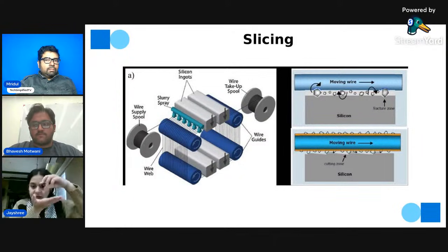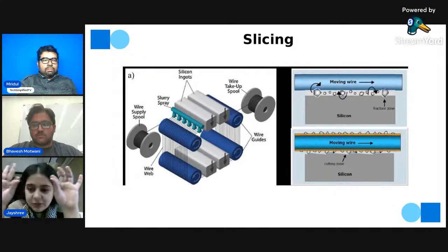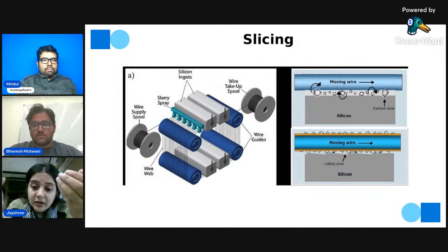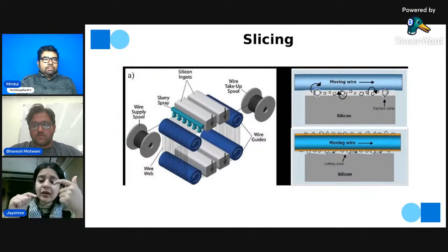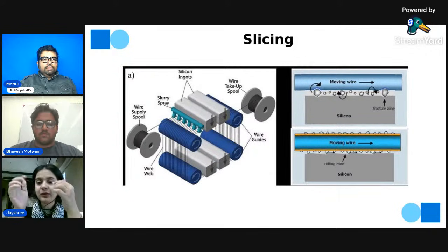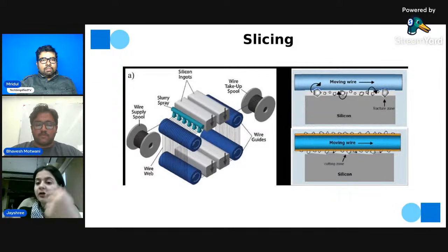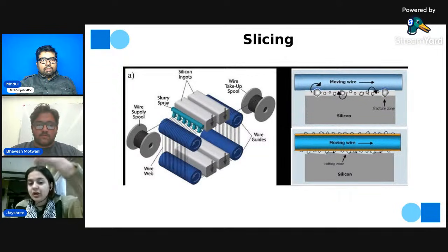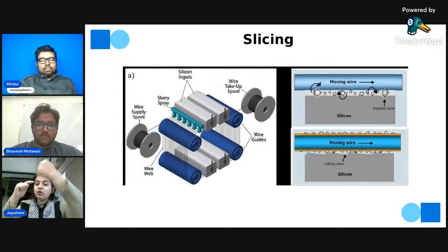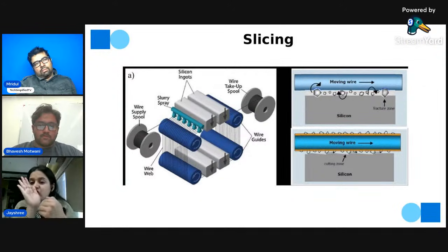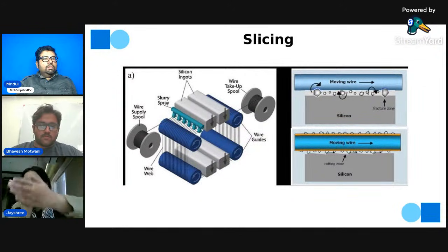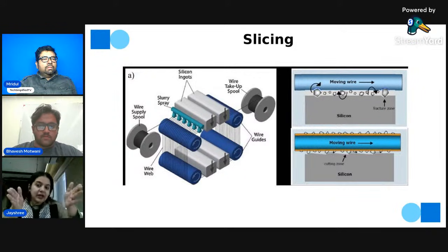Okay, so there is a diamond cutter. This wire has diamond inside it, so it's already a diamond wire cutter. There is automatic rotation going on, from one ingot to the next. With the sharp edges of the wire, it is going to cut the ingot into multiple slices.